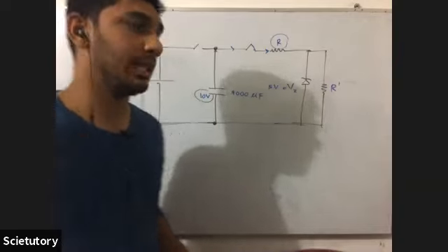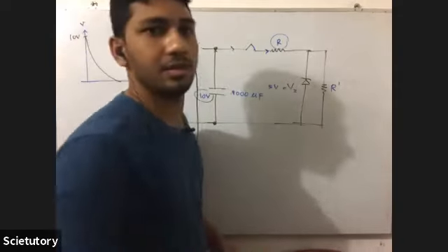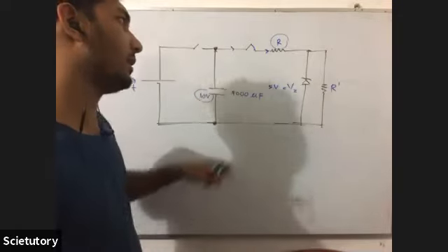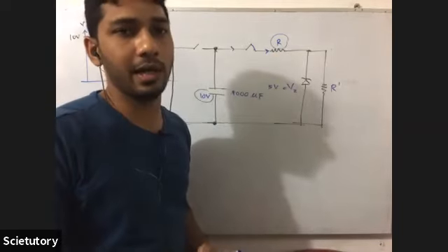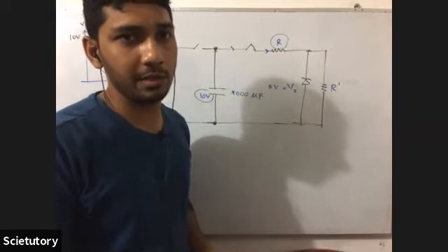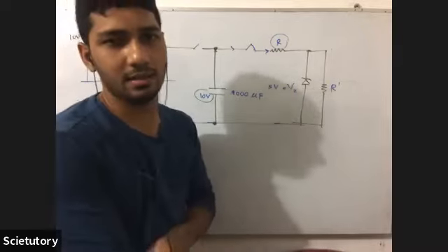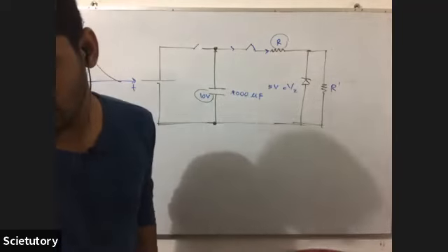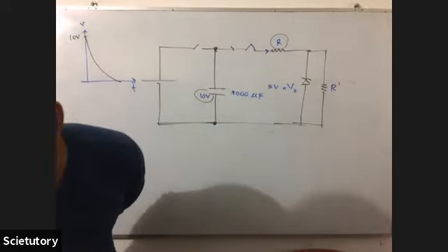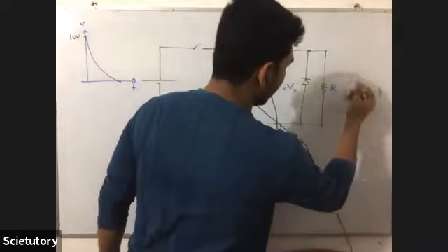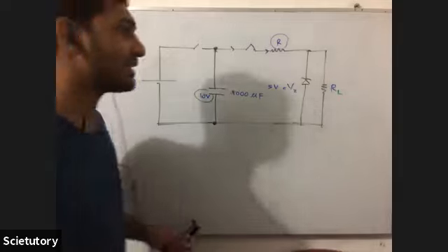First, you should imagine the circuit without the Zener diode. Then distribute the voltage according to the resistances. These are now connected in series, so you divide according to the voltage divider principle. But you don't know the exact values of these two resistances. But one data is there: RL, this is RL, not R dash, sorry. RL is actually a suitable resistor. That is the only data.